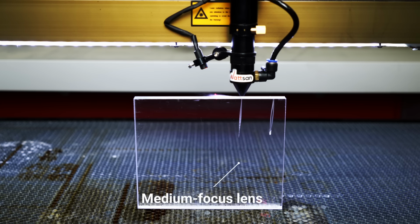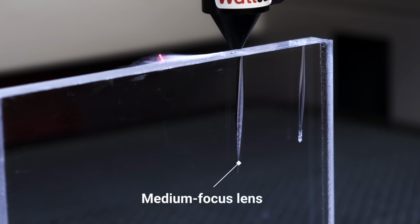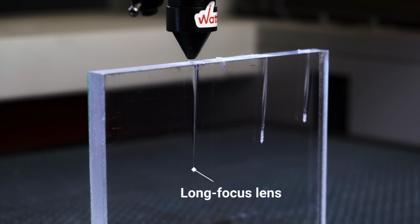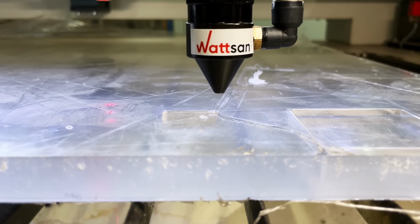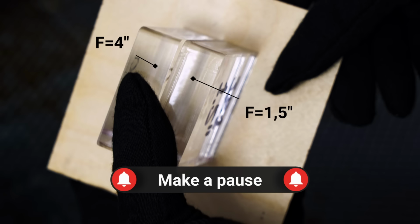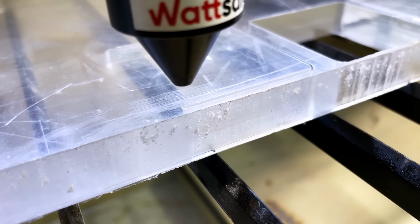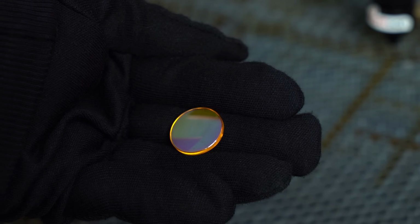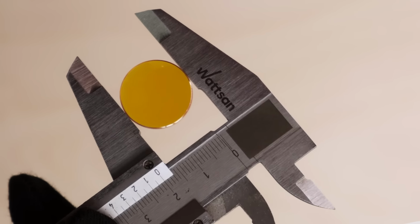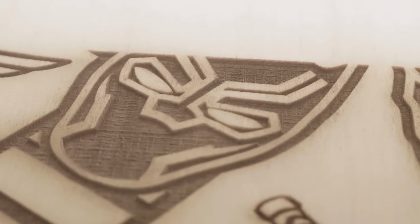The longer the focal length, the larger the zone becomes. This is why a long focus lens allows for cutting greater thicknesses without a noticeable slope on the edge of the workpiece, and also influences the maximum effective cutting thickness. Additionally, a long focus lens gets significantly less contaminated during operation because it is much farther from the surface of the material. A short focus lens has a smaller focus dot diameter, so it's possible to make more detailed images in high resolution with it.